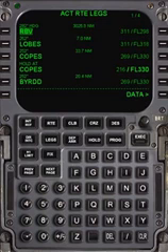The FMS mode is normally called LNAV or lateral navigation for the lateral flight plan and VNAV or vertical navigation for the vertical flight plan. VNAV provides speed and pitch or altitude targets and LNAV provides roll steering command to the autopilot.